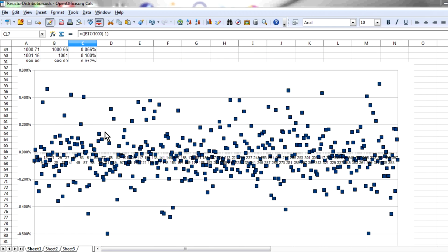And I guess the other thing to note is that the resistors 1 through 400 here are actually in sequence as I measured them on the bandolier, from one end of the bandolier to the other end. So there are no sort of oscillations or anything like that in there that are immediately apparent.